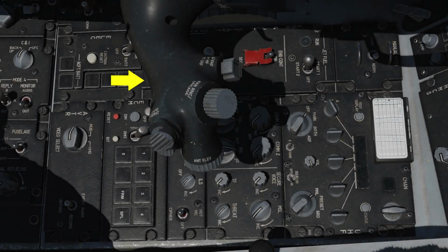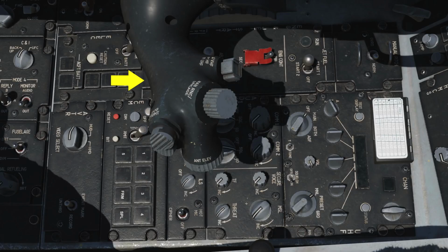The throttle moves in an arc with aft and forward providing thrust. Fully aft, the throttle is in the off position, but then moves to idle when we move forward over the hump. Moving the throttle forward over the next hump engages dry military thrust. Moving over that hump then engages the afterburner. The throttle is one element of the hands-on throttle and stick, or HOTAS control system.